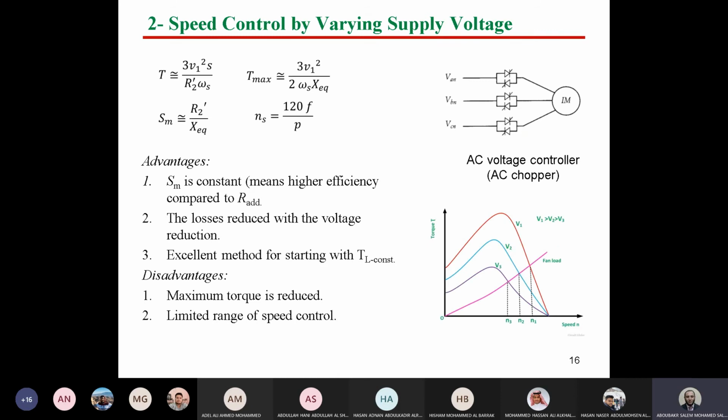Now guys, let's start another control technique, which is voltage control. We said before we can make voltage control. Again guys, in order to make any speed control we need to check some boundaries or the curve boundaries, which are the curve of torque at small slip, which means the linear part, from no load, very close to that point, to full load, which is high in this area. So this is the linear part. The other value is the maximum torque.